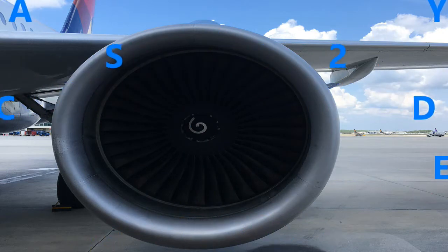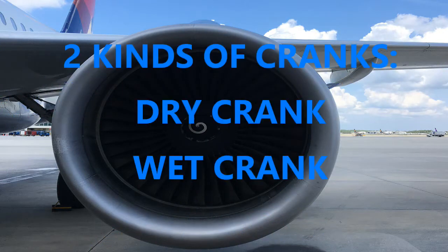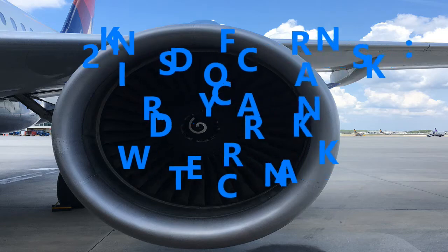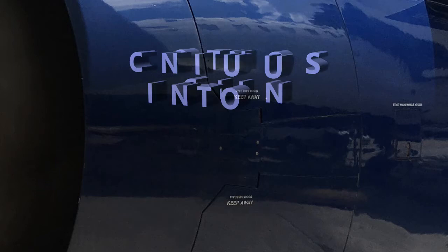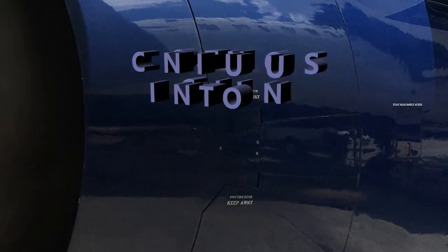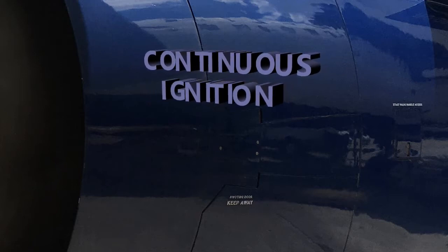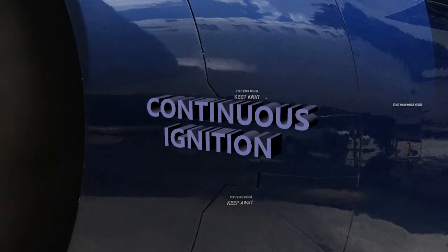Going through the combustion chamber, and wet crank obviously means that there is a fuel flow. So you've got a liquid, a fluid, as part of that sequence. Your continuous ignition can also be selected through the ECU. It can be done manually with the rotary selector, or automatically by the FADEC. Either way, automatic or manual, it's possible to have the continuous ignition.